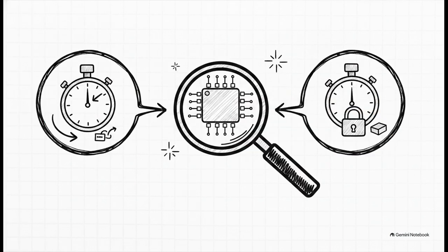Right, so once that shifting is totally done, we enter scan capture, and the timing requirements instantly change. Because the circuit is now generating an actual response that's being recorded back into the scan flip-flops, STA has to step in and check both setup and hold timing constraints. Basically, the data must arrive exactly on time, that's your setup, and it has to stay stable long enough to be securely recorded, that's your hold. This is what guarantees complete data integrity during the whole capture operation.